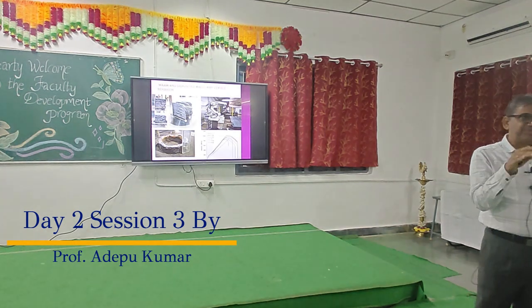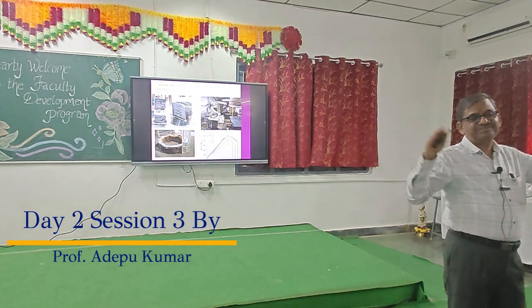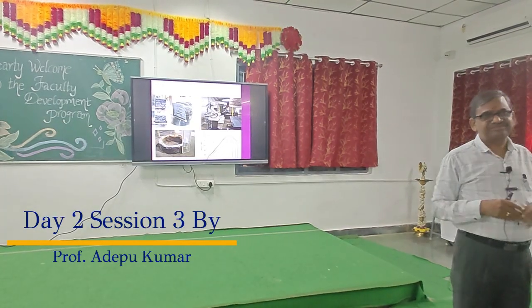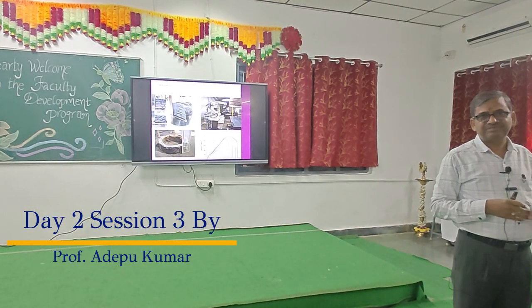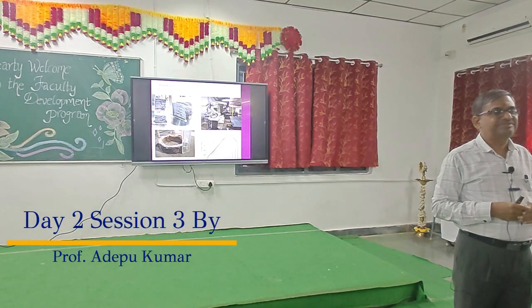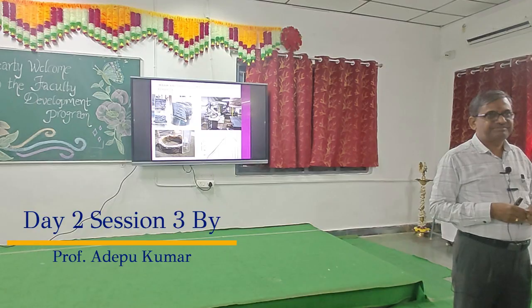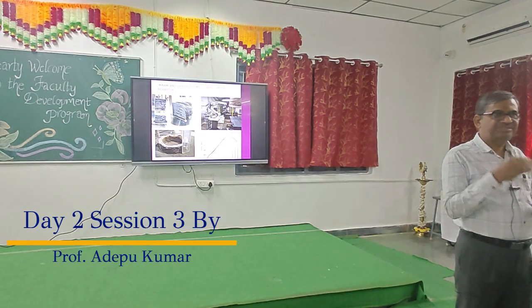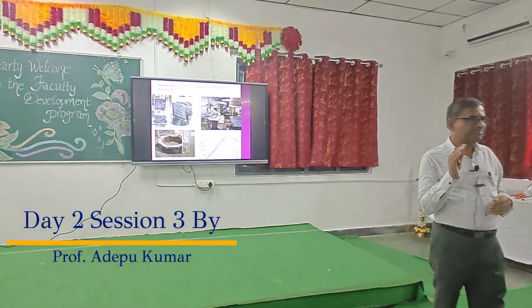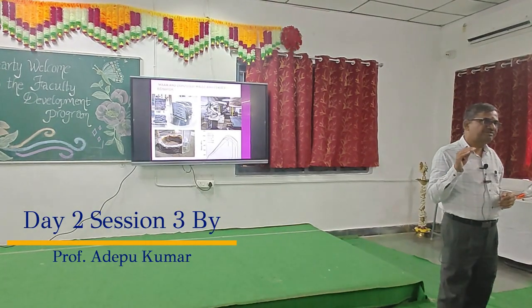So once the weld is completed, if you have a large distortion, then again you have to go for another forming process. That is, a secondary process is required. So to avoid that, why don't you minimize the distortion? So to minimize the distortion, what should I do? I have to supply the heat not continuously.